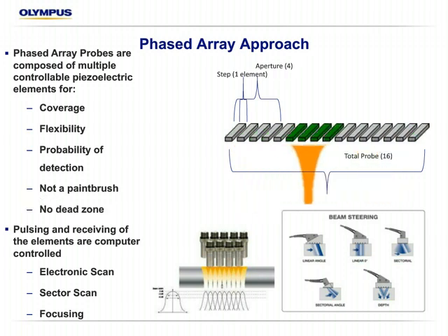So for many years in many industries they would use multiple single-element conventional transducers on a multi-channel unit in order to cover larger areas, but at some point you always have a dead zone. You see in the bottom illustration there. No matter how you stack different sensors together, unless you start to phase them and use a phased array type approach, you're going to have some dead zones in there, and you're only going to be able to have a certain amount of detection capability.